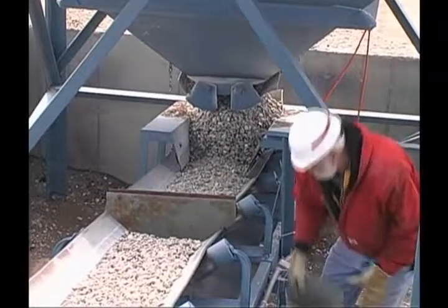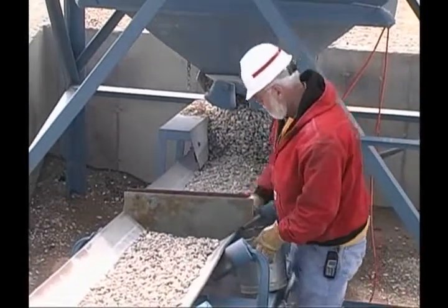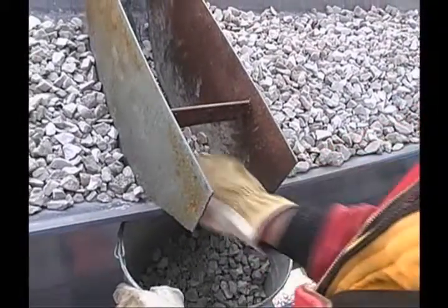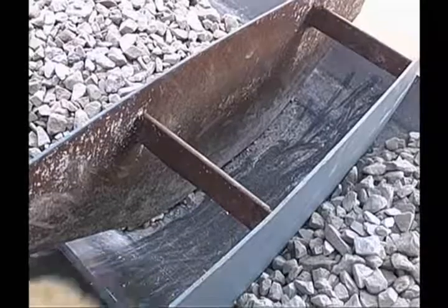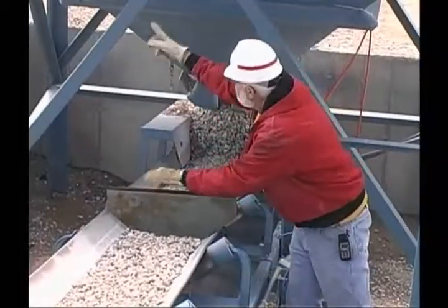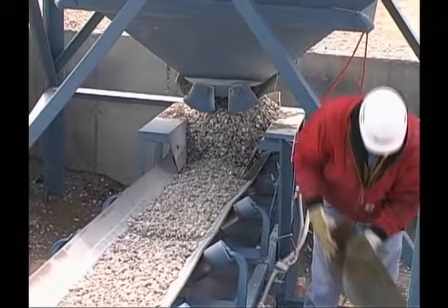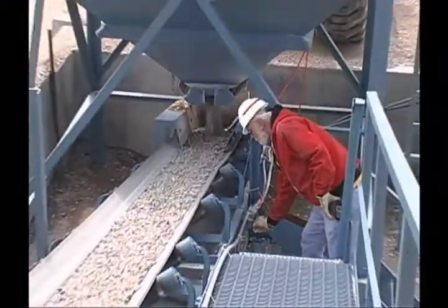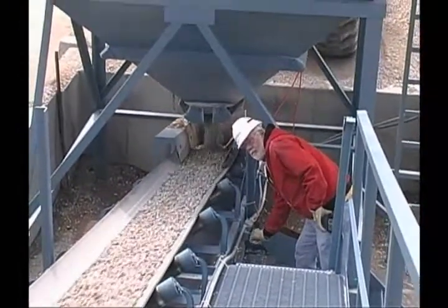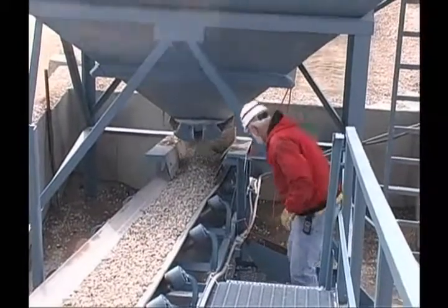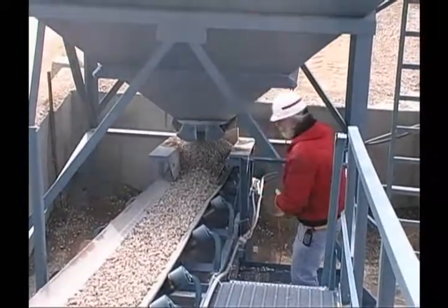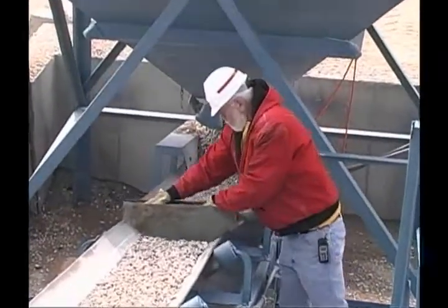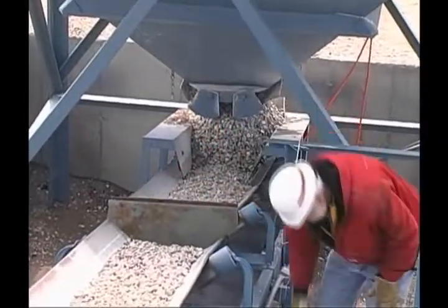Clean out all the material from the belt within the template and place it in the sample container. Remove the template and start the belt to run more material through the plant. Stop the belt again to take another increment. Continue this procedure a minimum of 3 times. More increments may be needed to reach the minimum sample size recommended. Running more material on the belt will give a more representative sample.